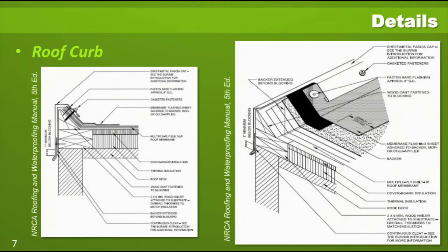Then asphalt plastic cement can be installed before putting on an additional flashing ply of material up that curb. That would be attached with fasteners. The fasteners would end up being covered by the metal edge flashing, and the metal edge flashing fasteners will be installed in the sloped portion to give it better water resistance than if the fasteners were in the top of the edge flashing.